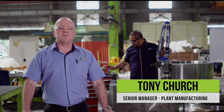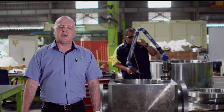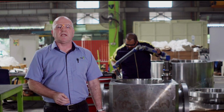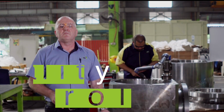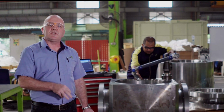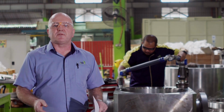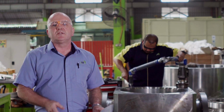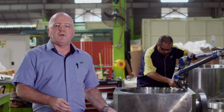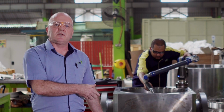My name's Tony Church and I'm the Senior Plant Manufacturing Manager for MIR-Valve Malaysia. Today we will be talking about this valve here, which is a 20-inch Class 300 subsea valve. Material of construction is carbon steel body with full 625 Inconel inlay. The valve will be operating at a depth of 40 meters subsea. Design and manufacture is to API 6D SS. I will introduce you to Bob, our QC inspector, who is performing some of the critical inspection.